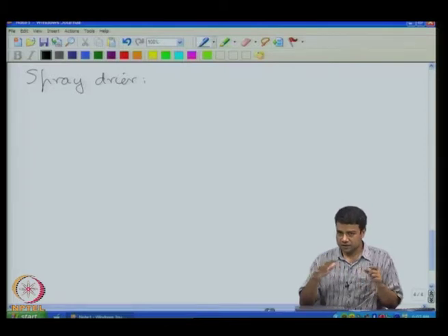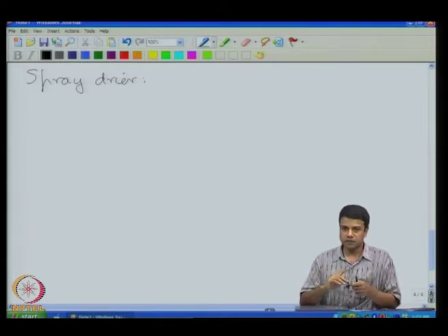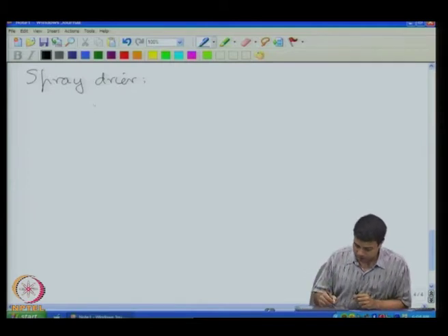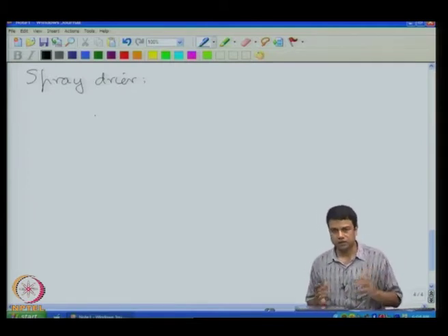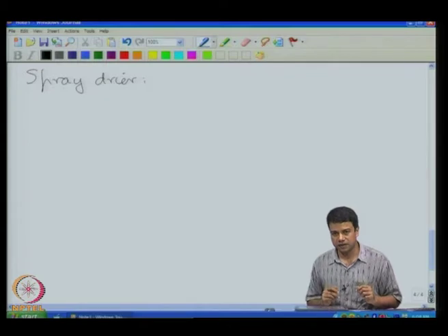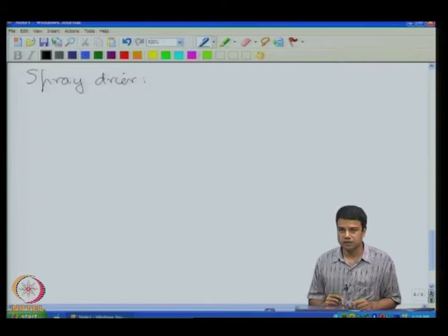As these droplets of the liquid fall in the spray dryer, they come in contact with hot dry air, and that dries the droplets and gives you solid particles. The key crucial thing in the spray dryer is that the particles have to be fully dry by the time they settle on the walls of the dryer, otherwise they will agglomerate and form a sludge. For this reason, spray dryers are actually very tall columns. They typically are 10 meters in height and 1 meter in diameter. We will see when we do dimensional analysis the reason for why these are of such large dimensions.